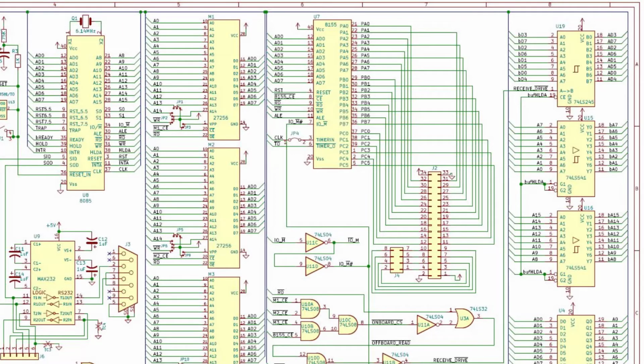Okay, so this flips back and forth with each read. If it's an onboard read, the bus transceiver drives data onto the bus. If it's an offboard read, the bus transceiver receives data from the STD bus. And that's why this line is called either receive or drive. So it reads the STD bus during an offboard read, but otherwise drives the processor AD lines onto the STD bus.